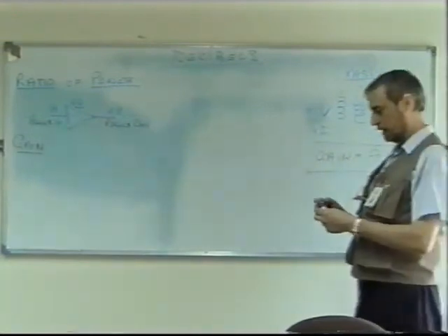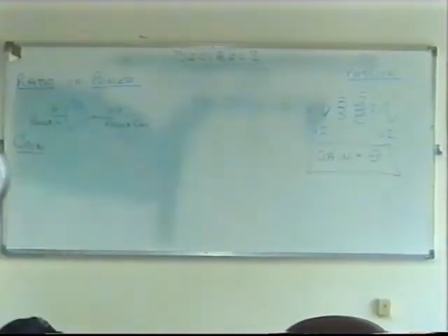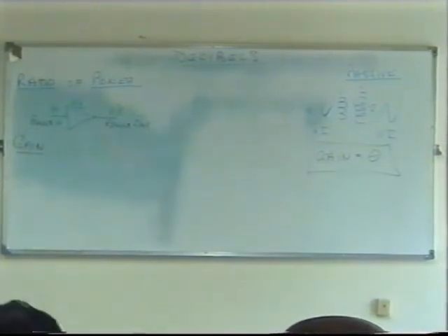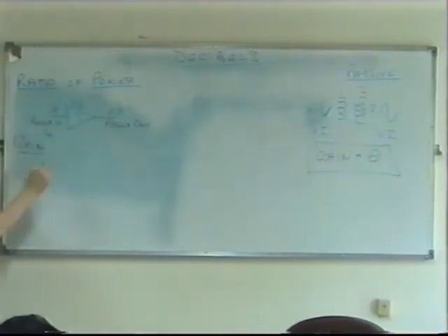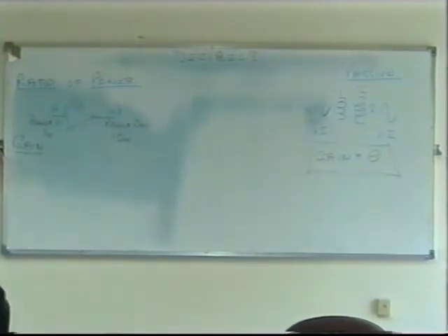The only way you can add power is if you use an active component. An active component takes a DC power and changes it or adds that power to the signal. Now here, in a power amplifier, let's say I have 1 watt input and 10 watts at the output. Now this is power, not voltage, not current. We don't know what the current and voltage is, that could be anything. We can actually use a transformer at the output to change the ratio to anything we want. Again, 10 divided by 1.